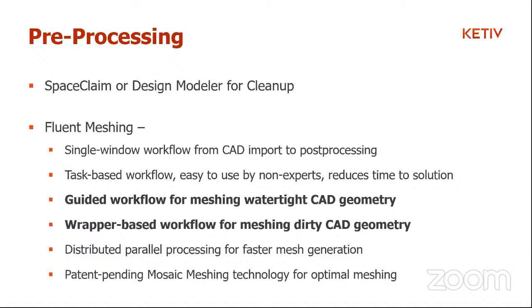So Fluent itself has two extremely capable guided meshing technologies. We've already done AVAs in the past. If you're curious, please make sure to check them out. What I would be using for this sort of an analysis would be the fault tolerant meshing workflow, which again wraps your mesh around the dirty CAD geometry.